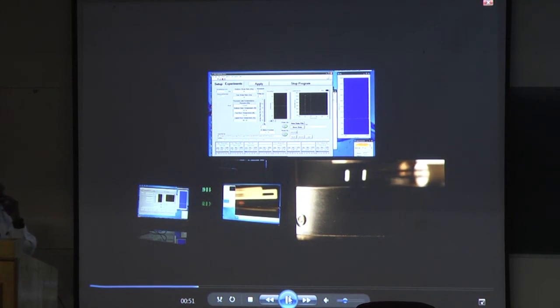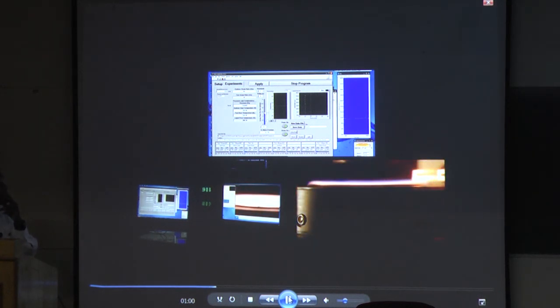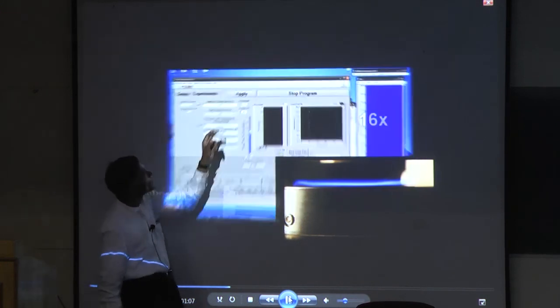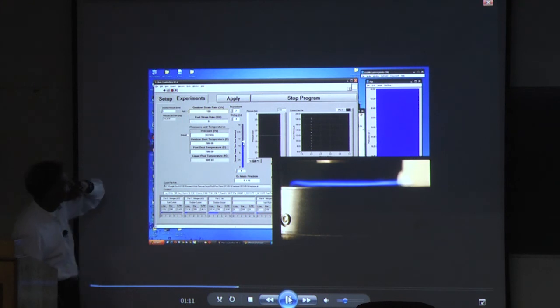You can see the igniters come in. That's the flame. That's the igniter. What we're doing is the extinction. So now automatically the strain rate is increasing. And you watch the pressure, very little fluctuation of pressure. We make very accurate control of the pressure. So now the flow rates are increasing continuously, and you will see the flame extinguish.